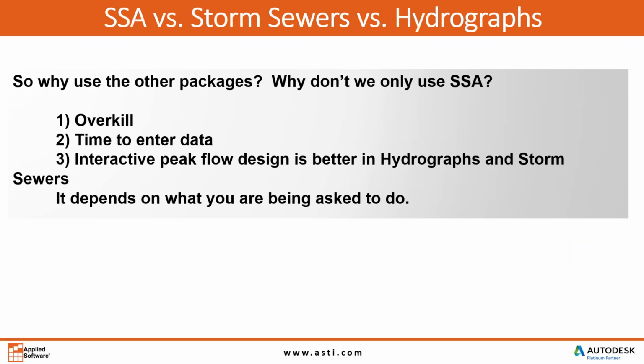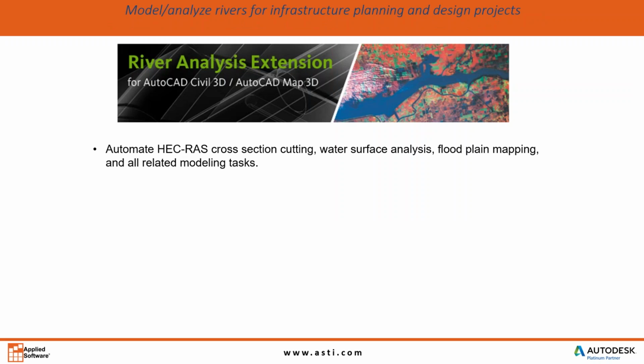So why use other packages, or why don't we use SSA? Sometimes it's just overkill using SSA, and the time to put the data in, you could do it with HydroFlow. So it kind of depends on what you're being asked to do. But clearly, if you're doing pressure and sanitary, HydroFlow is not going to be that for you.